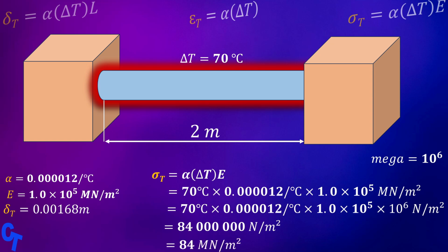In most cases, the problem won't be easy like the one we solved. We will have statically determinate and indeterminate structures. A statically determinate structure is one that is stable, and all unknown reactive forces can be determined from the equations of equilibrium alone. A statically indeterminate structure is one that is stable, but contains more unknown forces than available equations of equilibrium.